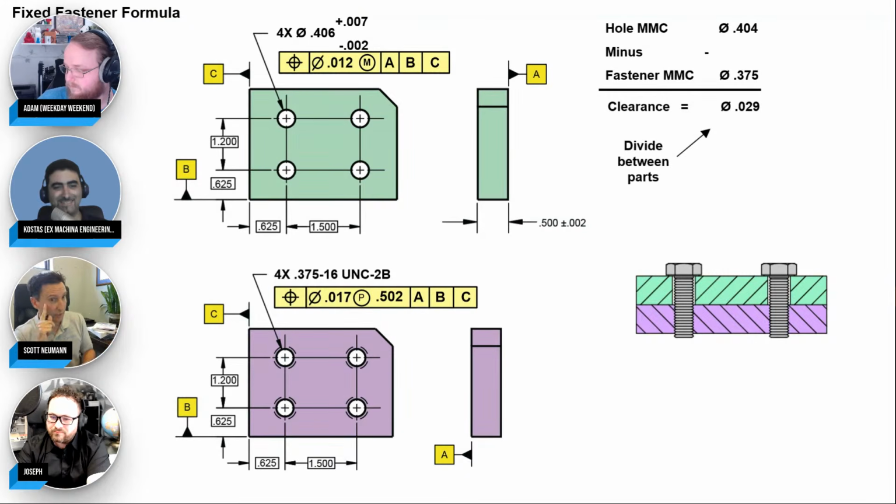Now, a good quality engineer is going to look at that and say, ooh, I see you want 17 on the pitch, but I want to make a cheap gauge on the minor diameter. So I'm going to artificially guard band the tolerance myself. That's what I recommend quality do. You guard band artificially.